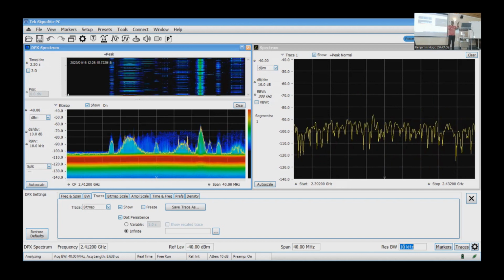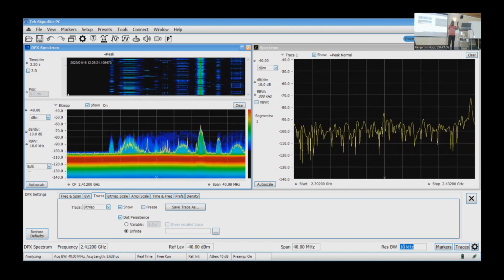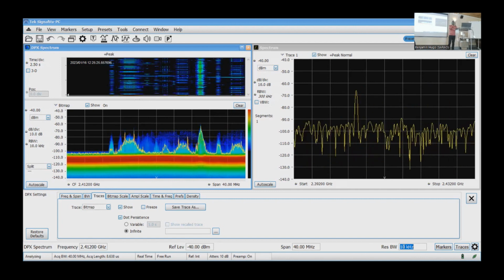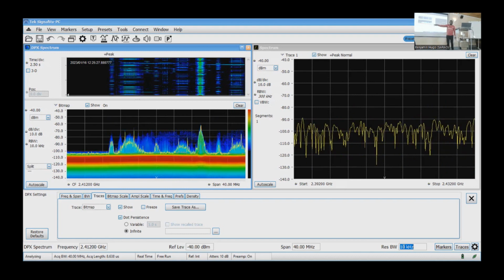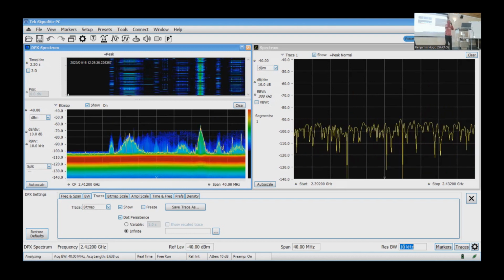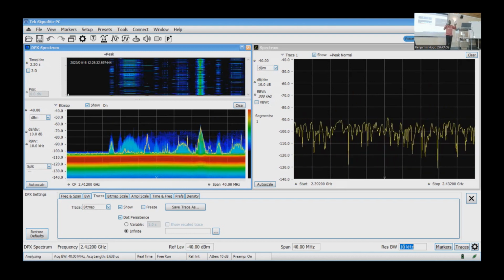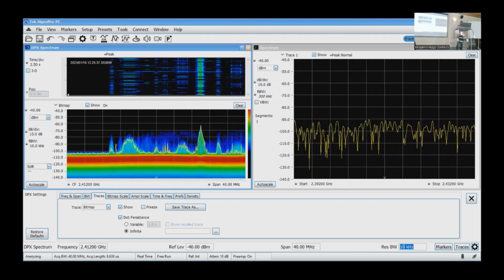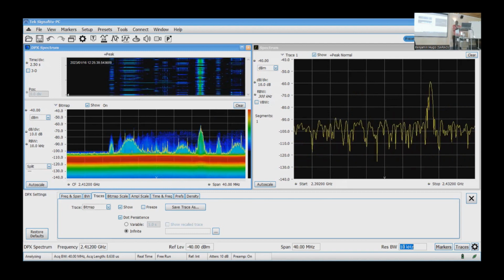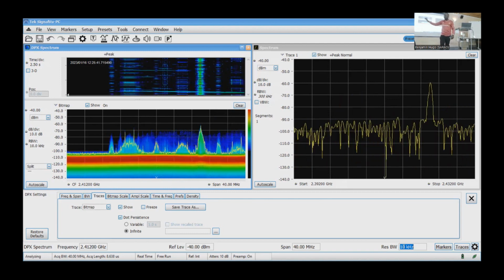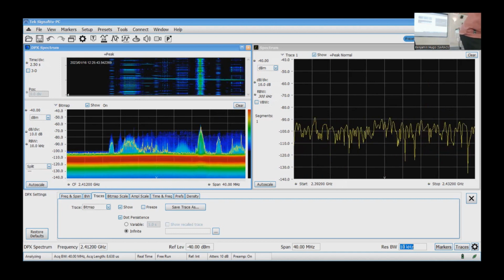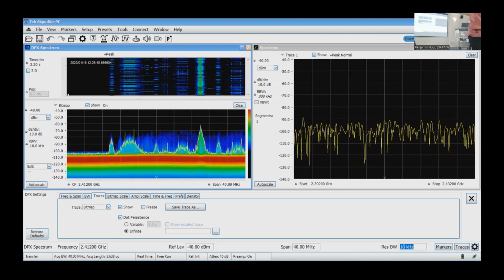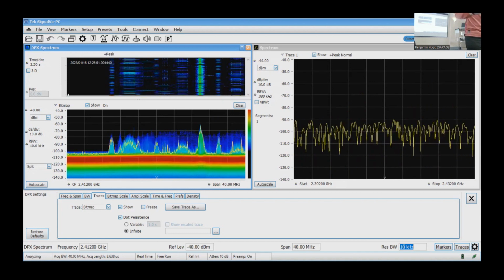So just to give you a rough idea, I want to do a quick scan of the RFI environment within a particular frequency band. I use the omnidirectional antenna to capture everything. Once it has captured everything, I'm going to identify specific frequencies that I want to focus on. Then I transition because I want to locate the exact position where that radiation is coming from. I can't do that with a wideband omnidirectional antenna.